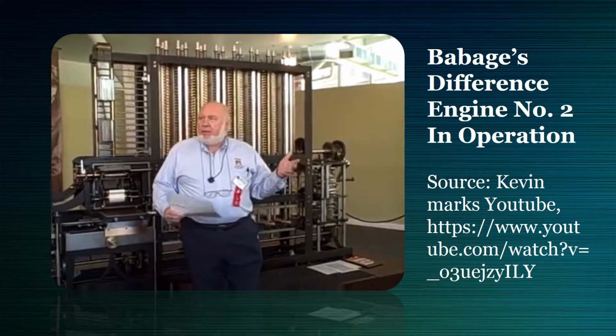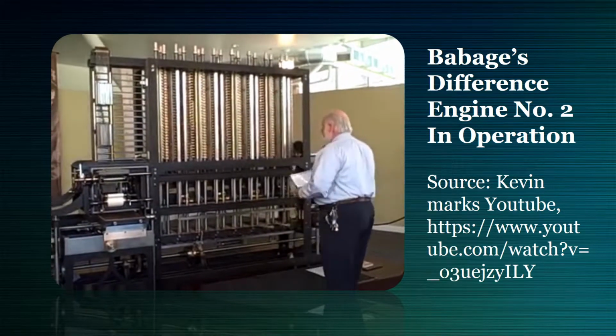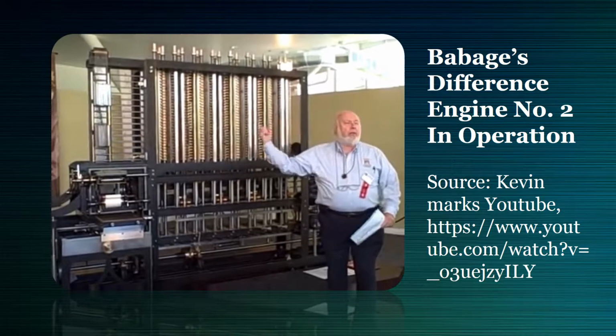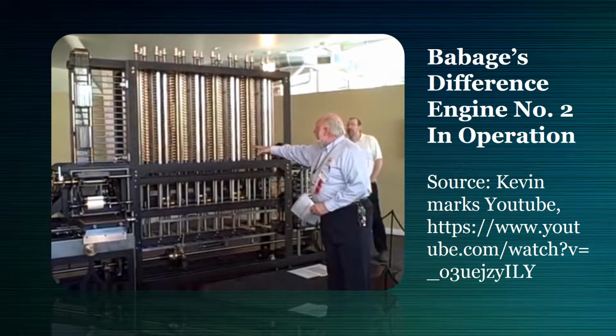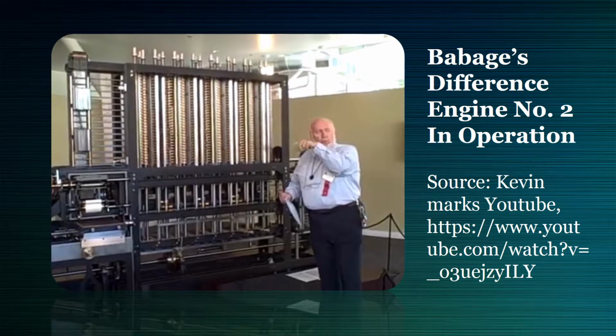Now you might say to yourself, well, how's that possible? Well, the odd column has the numbers on the number wheels that go around in a counterclockwise direction. In order to count them down, you turn the gear counterclockwise. And when you do that, something like the 8 gear will go 8, 7, 6, 5, 4, 3, 2, 1, 0.